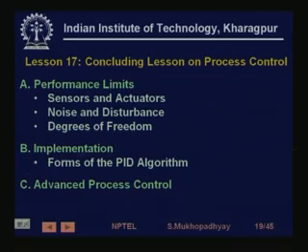All actuators have their rate limits as well as position limits. So, even if you think a very large input can be given to a plant, it actually cannot be given because of actuator limitations, and it is for these reasons that the so called theoretical responses cannot be obtained. So, these constraints put a limit on the performance of the control loop.